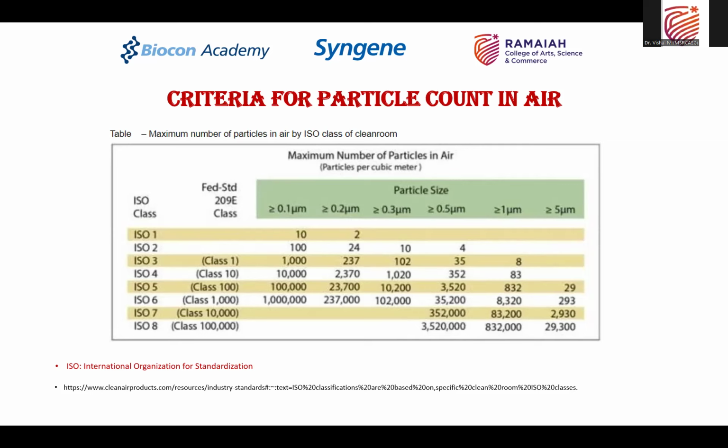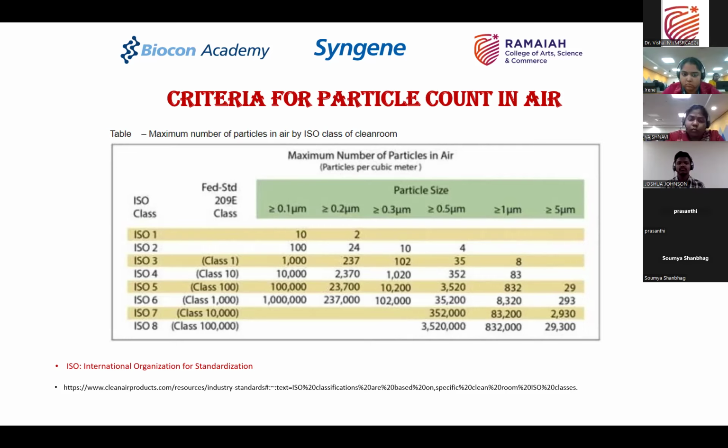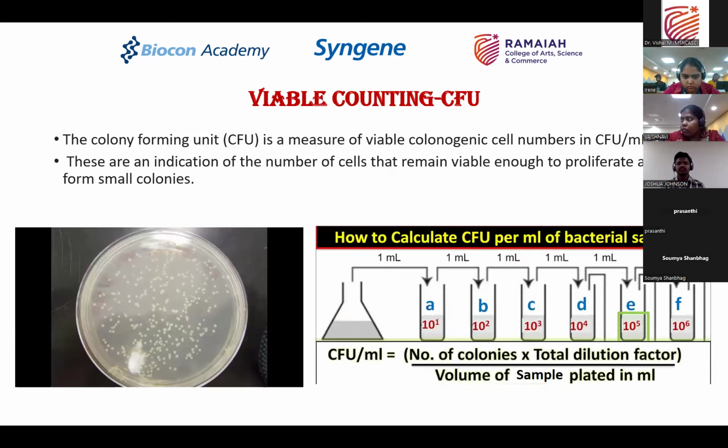If the particle count is more than the given standard, it has to be controlled. So there should be controlling devices or systems to control the non-viable particle count in the specified area. This table indicates how many particles and what size of particles are allowed, maximum, in the area according to the different ISO standards. So this is about the non-viable particle count in the air.